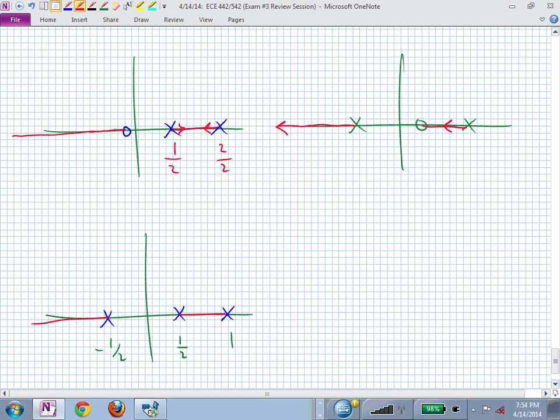What's my pole zero excess? 3, which doesn't have to always equal the branches, does it? But now I have 3 branches that are starting in the finite z-plane, and all 3 are going off to infinite zeros. Where are those infinite zeros located? In what angular directions? Do you remember?